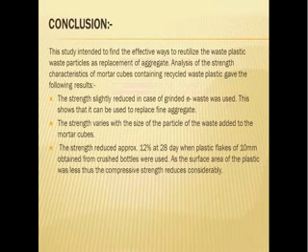From the overall study we can conclude that the strength slightly reduced in the case of ground e-waste, so this can be used as a replacement of fine aggregate. We also concluded that strength varies with the size of the particle. In the case of the bottle waste, the strength reduces up to 12% at 28 days.